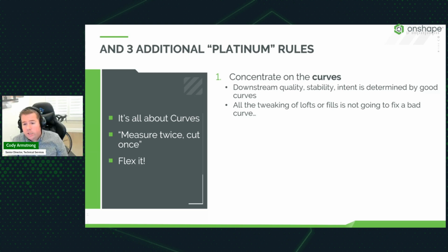All of those things will lead to smoother surfaces, designs that update better in design intent. So it really is the foundation of good surface modeling: focus on the curves and how you generate those curves. Even the nuance that I was showing you a moment ago of using isoparametric curve to split rather than a projected curve is another curve tip, because we really want the resulting geometry to be as smooth as possible, as clean as possible.